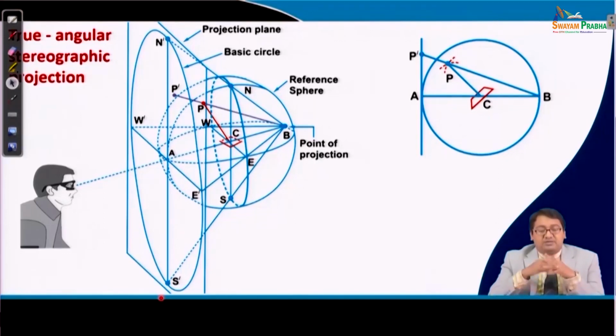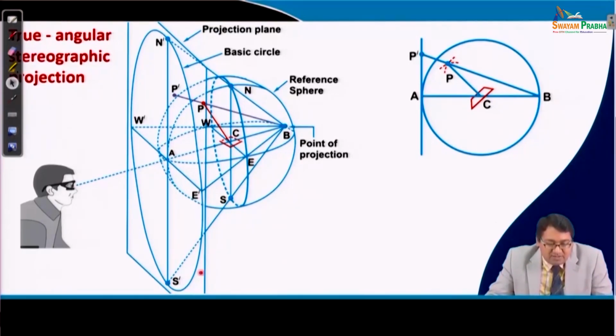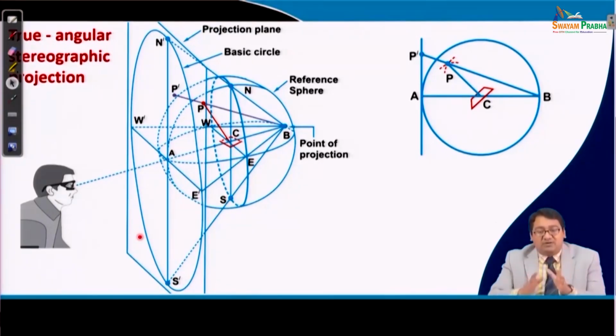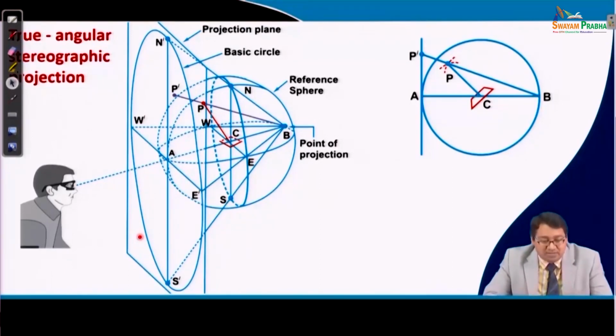So you see that the poles and the great circles in the 3D stereogram, which is obtained from the unit cell kept at the origin at the center of this 3D stereogram, can be converted into a 2D image, which is basically known as an equiangular stereographic projection. This equiangular stereographic projection has all the information of the crystallographic planes and directions and angular relationships between them, because they are truly angular.